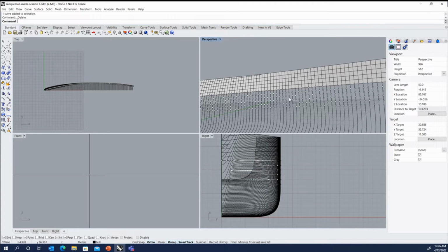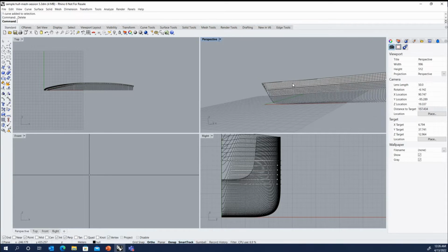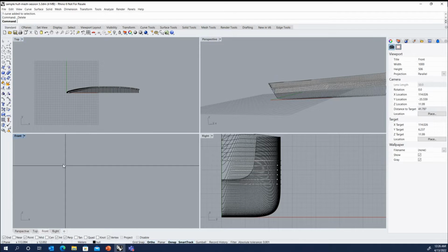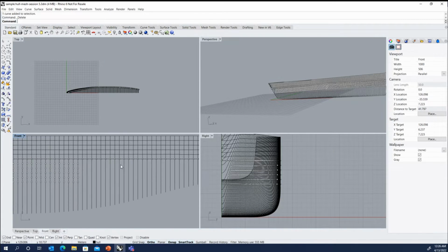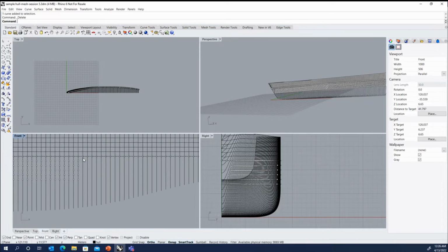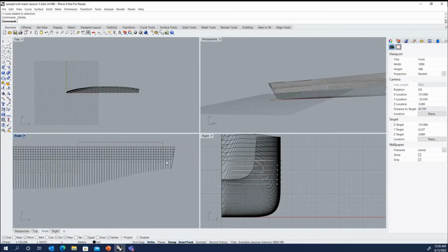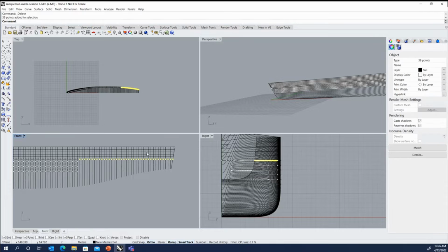I could have selected all those curves again and said mark the curve end after deleting that point that was near it. But it's probably easier to just use the points from the other mesh because you know exactly where you need them. But we have a bunch of extras at the end here, but it's easy enough to come in and select those. And if you're worried that you may have selected something else, whenever you drag around a group of objects, it tells you everything that was selected by that drag. So I only got 39 points added.